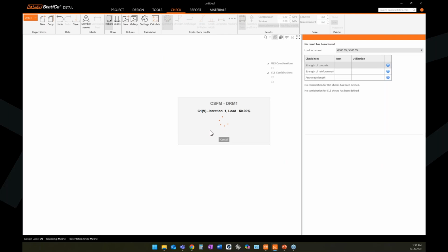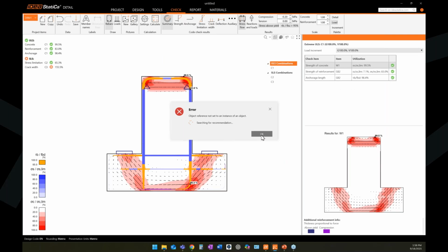So as I said, now the nonlinear analysis is being performed. It consists of 3 steps. Preprocessor, when it does the meshing, it connects reinforcement with the mesh automatically. The middle part is the analysis itself. The last part, post-processing, checking the results. And we actually see the results.